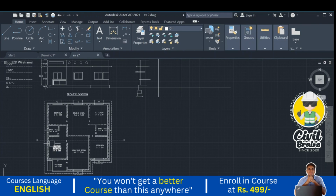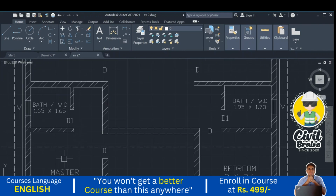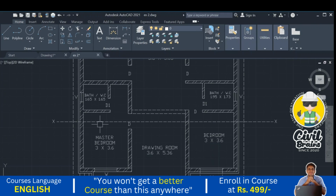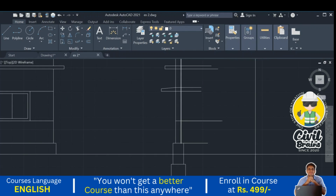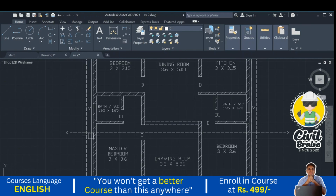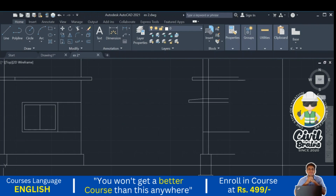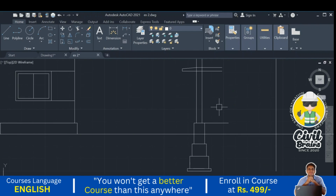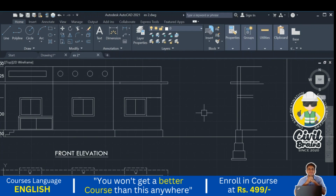The line is crossing the first wall, second wall, third, and fourth wall. For all the walls we need to draw, but here we made one small mistake: the section line is not crossing the window. If the section line is crossing the window, then only we need to draw the window here, but here it is not crossing the window, so no need to draw the window. So I just delete this one. I just use this sill level. I just delete the chhajja. But the lintel we need to keep over there.